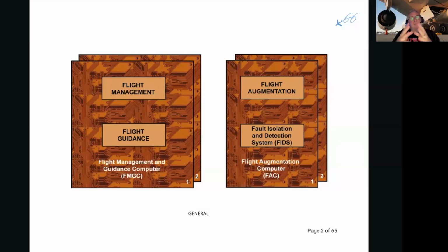I'd like to tell you the way I quickly distinguish the difference between flight management and flight guidance. I would say flight guidance is what Airbus describe as short-term navigation, which is, if you're looking at an ADI, up, down, left, right. It guides you for immediate short-term navigation. So up, down, left, right, which is your ADI, your sky-ground picture.